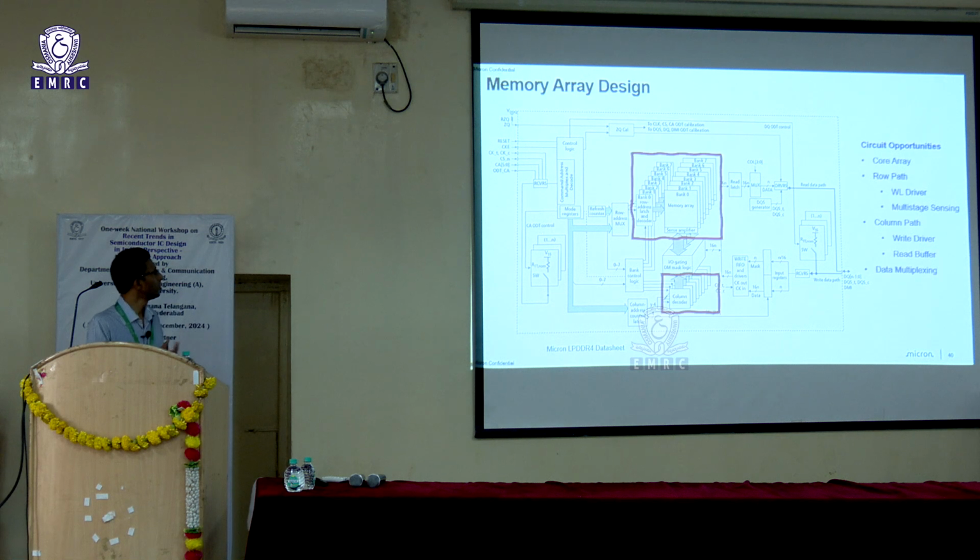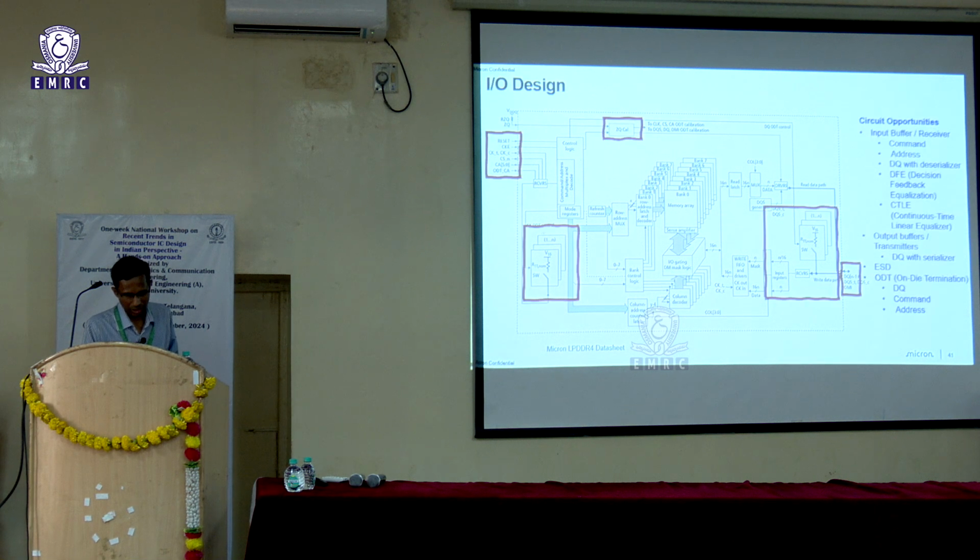And then we also have a memory array. As I said, it's organized as multiple banks here, and you have different row address and column address things that are interfacing your bank. So all that is part of your memory array. And then I/O design. So all the I/O pins that you have here, and this is something that I didn't talk about, the ZQ calibration.